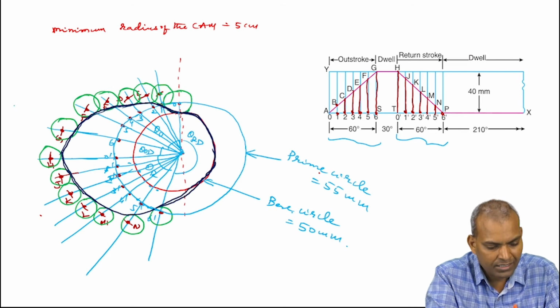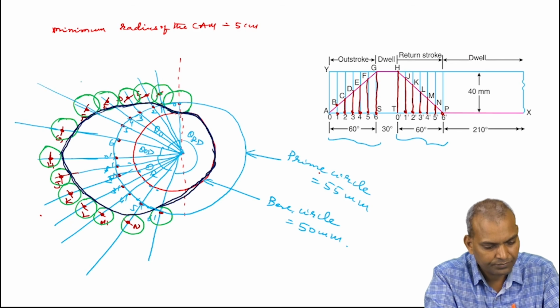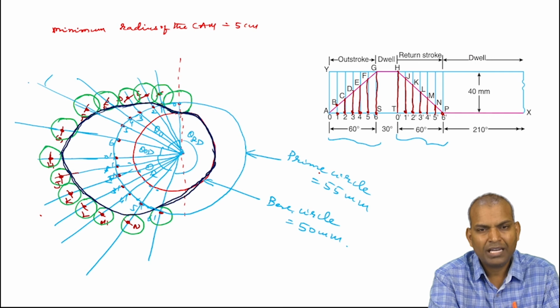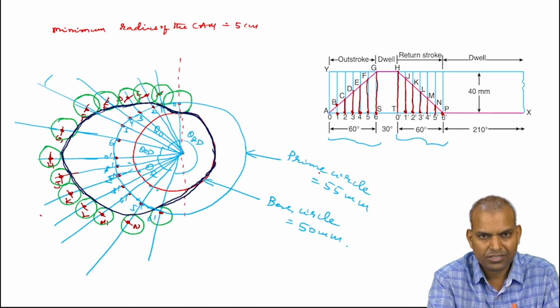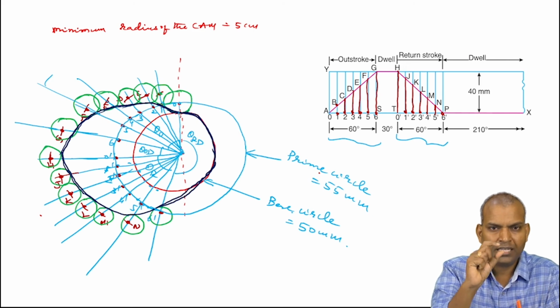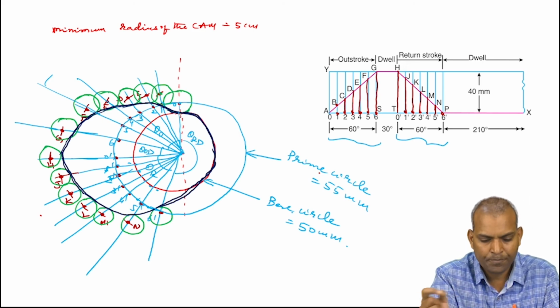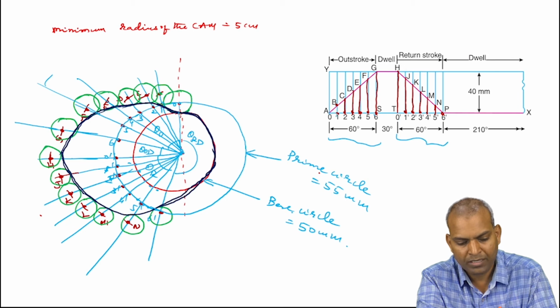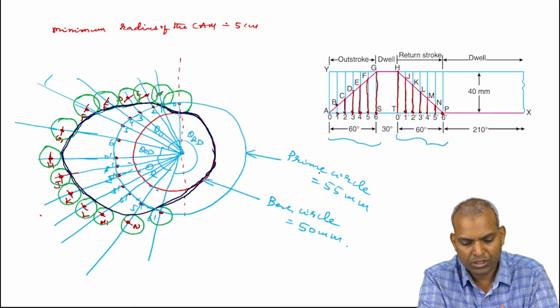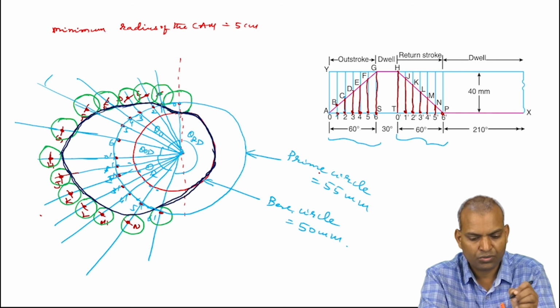These are all our radial lines. After drawing these radial lines, you mark the vertical distance of the follower, or vertical displacement of the follower. Take the displacement from the displacement diagram. From point 1, mark 1 to B, this is the point B. Similarly, 2 to C, 3 to D, 4 to E, 5 to F, 6 to G.